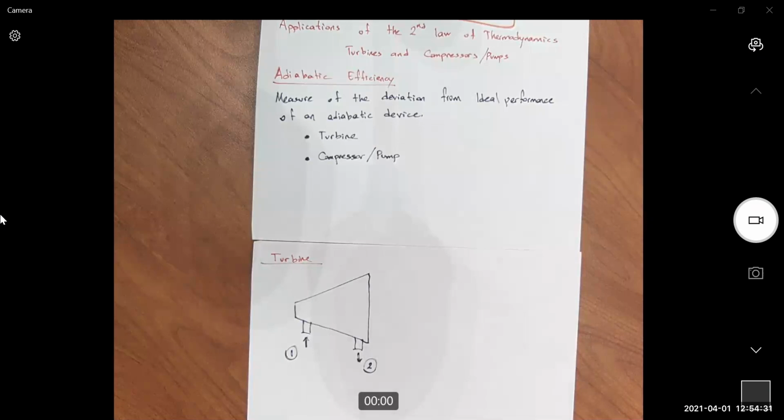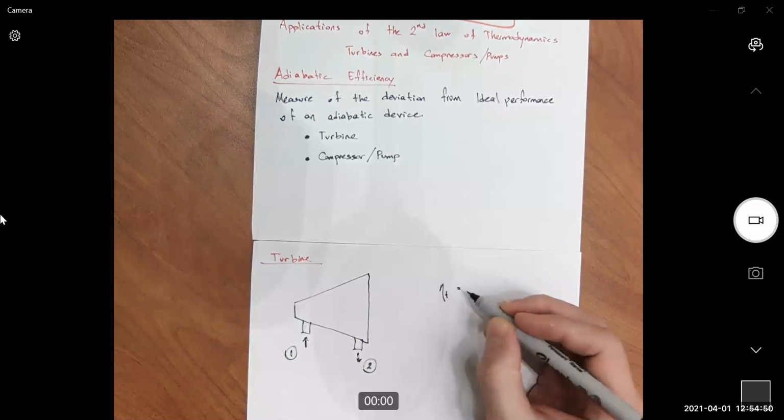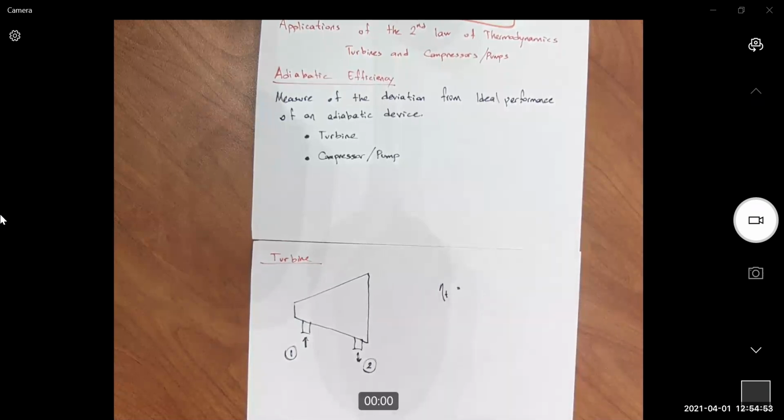the entire system deviates. The entire system falls by the irreversibility. It's not perfect anymore. So that's what we are going to do today. The thermal efficiency of a turbine was net work divided by Qn. But for adiabatic efficiency, we compare the ideal case and the actual case. Actual case meaning that irreversibility is introduced in the system, due to the second law.